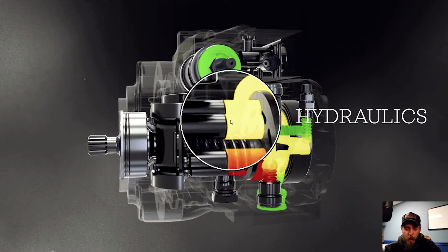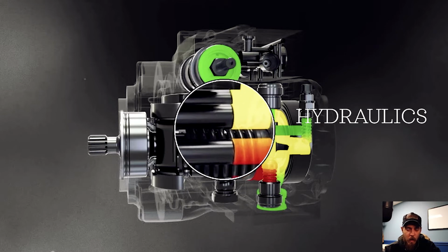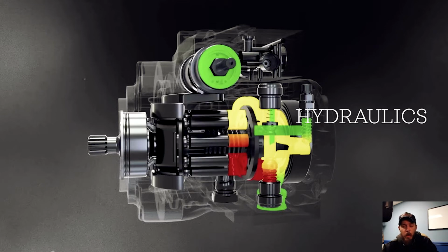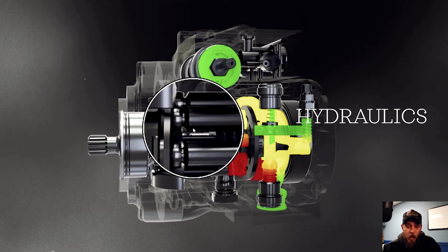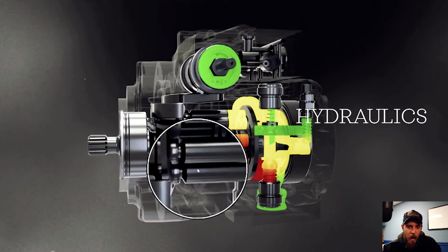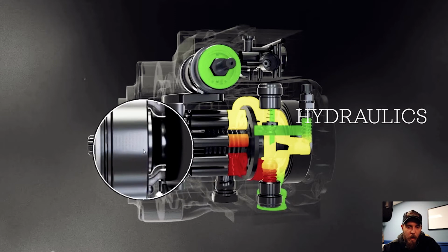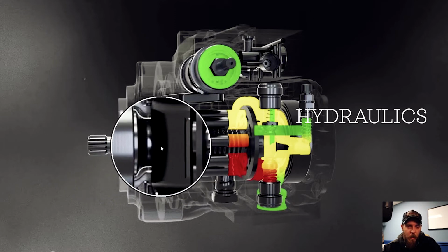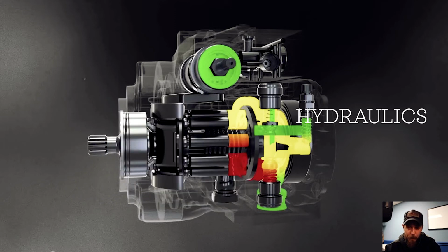Looks a lot like a revolver barrel. You've got your pistons here. So your barrel is similar to your engine block, and your pistons are very similar to your regular pistons. Some differences you'll notice here are the slipper right here and your slipper plate. And then this here would technically be considered your drive shaft.